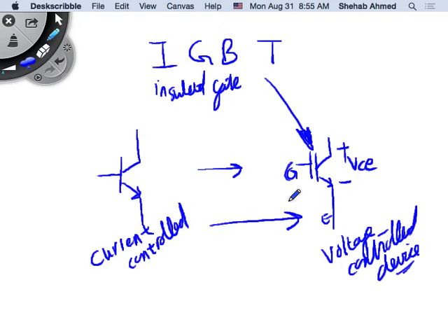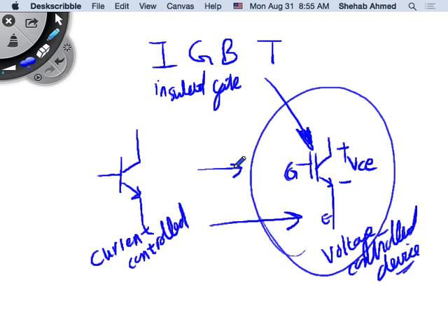So that's beauty, right? Because you've combined the benefits of the MOSFET and the benefits of the BJT in a single device, and that is the actual workhorse of the bulk of power electronics. If you open almost any power electronics device, you will find the IGBT, almost. At very low voltages, no. At very low voltages, the MOSFETs are cheaper. Okay, so at very low voltages, MOSFETs are cheaper.